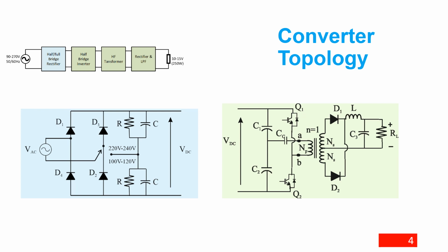The DC/DC stage has a half-bridge converter composed of Q1 and Q2, a high-frequency isolation transformer, and two rectifying diodes D1 and D2, followed by an LC filter stage. There is a small coupling capacitor, CC, between the switches and the primary side of the transformer. This capacitor prevents a flux from building up in the primary winding and causing the transformer to saturate.